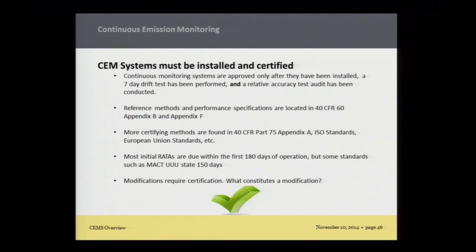Just something, you mentioned how you have to do at least 9 runs, 12. I don't know if it's the same in most groups, but I know for us, especially when I was learning it, what we were told was you have about 3 runs, and after the 3rd run you're committed to the RATA testing. So if you look at the first 2 runs and see how close your numbers are to your RATA numbers, you can call it off, try to figure out what's wrong and schedule my RATA a week later or whatever. But for our regs and our permit, after we get past the 3rd one, you're committed, you must finish.